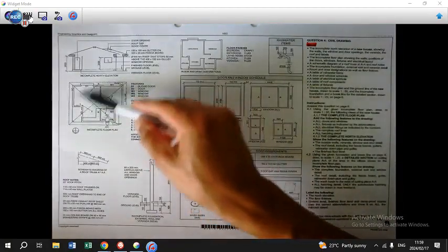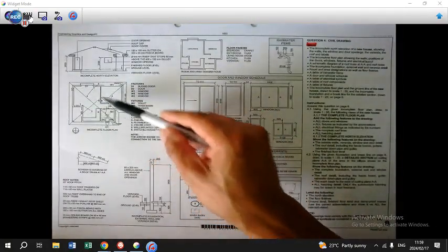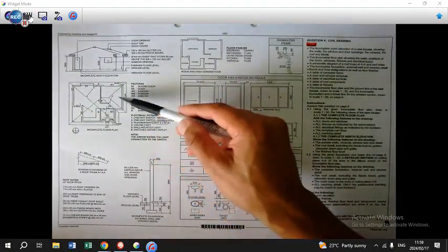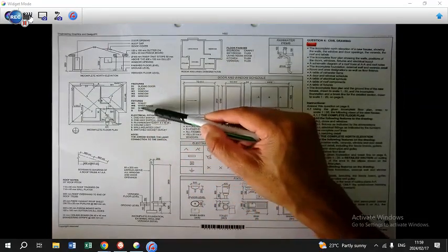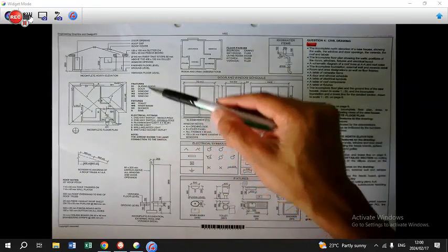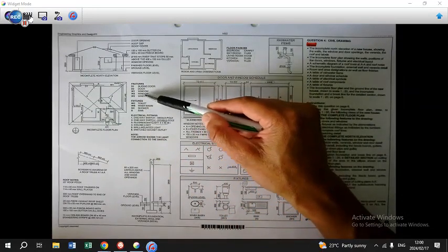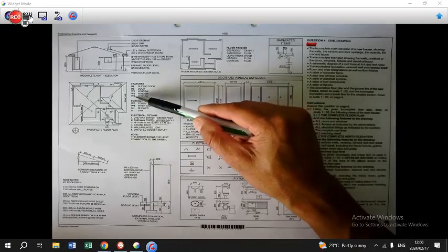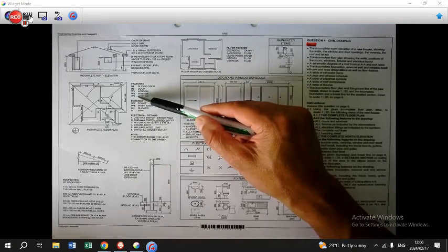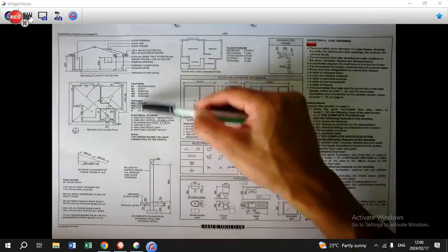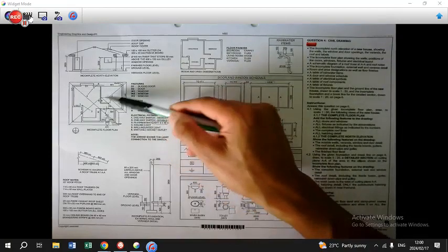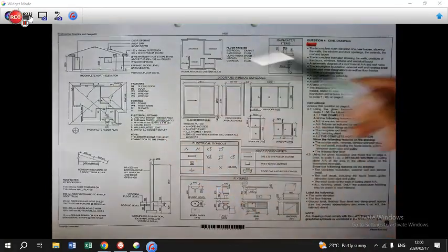Here you are going to find the incomplete floor plan, and it shows you all the information, and that includes the electrical fittings, the fixtures, which are all the bathroom items. You have the features, which are your sliding doors, your normal doors and all your windows, and it's indicated via symbols of W1, W2, W3, D1 and D2. So you need to look for those symbols on the actual floor plan.